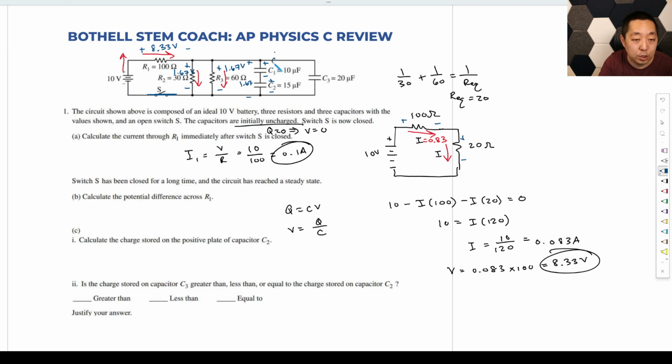So it's the same amount of charge, whatever it is. So the voltage drop is Q over C1. This voltage drop is Q over C2. And those have to add to 1.67, right? So you can say Q over C1 plus Q over C2, and it's the same Q, has to equal 1.67 volts. Now, this is equivalent to just finding the equivalent of series capacitors. That's where that actually derives from. Use the equivalent, 1 over C equivalent, right? And it's the same thing.